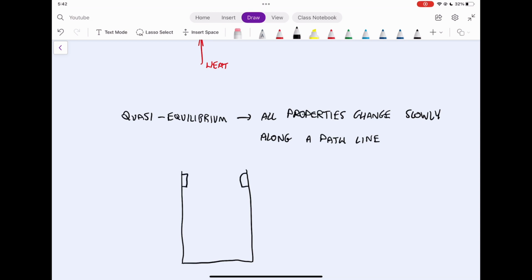So we're going to illustrate an example of how we use this quasi-equilibrium analysis if we had a piston cylinder with, let's say, some blocks of 1 kilogram weight each. So if we assume that we start with a system that has air at pressure 1 and volume 1 and has these blocks added on top of the piston cylinder, these blocks are going to somehow compress the air inside the tank by a certain amount based on the weight.